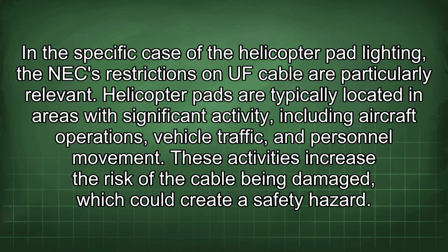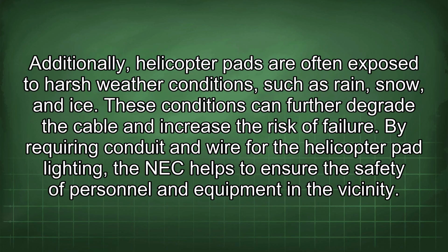In the specific case of the helicopter pad lighting, the NEC restrictions on UF cable are particularly relevant. Helicopter pads are typically located in areas with significant activity, including aircraft operations, vehicle traffic, and personnel movement. These activities increase the risk of the cable being damaged, which could create a safety hazard. Additionally, helicopter pads are often exposed to harsh weather conditions such as rain, snow, and ice. These conditions can further degrade the cable and increase the risk of failure.